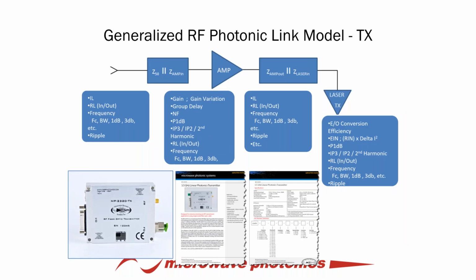One of the things that you can do is engage with us or engage with other members of your team to try to conduct a link budget analysis. Now, what we do here is we have the same process. We can help to write a performance boundary around the fiber optic link until where we can define each aspect of that system in terms of noise figure, traditional linearity characteristics, harmonics, and allocate that performance across the transmitter.